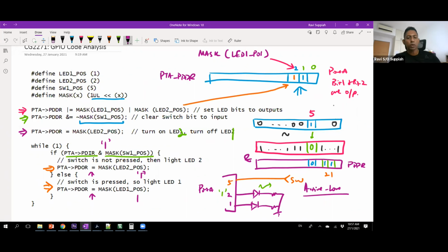So the way you write your code, whether you use bit masking or direct write, all these are important, and this can cause a lot of confusion in your lab. If you write it in a particular way without realizing, then when you are trying to test it, you may not see the correct output, but actually it is correct. It's just that your driver was written to either use bit masking or not, and then you see some other funny behavior. Later I will show you more on that when we are discussing the lab.